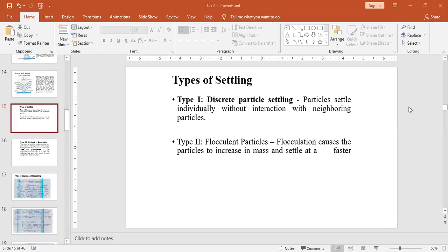Okay. There are two types of sedimentation process. The first process is plain sedimentation and the other is sedimentation with coagulation. First of all, I will explain plain sedimentation. Plain sedimentation is when the impurities are separated from a suspending fluid by the action of natural forces alone, or simply by gravitational and natural aggregation methods. This process is known as plain sedimentation.